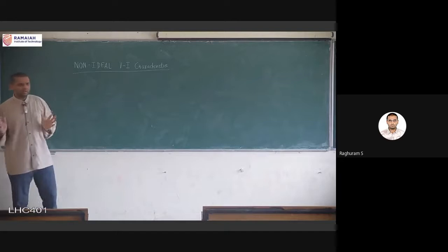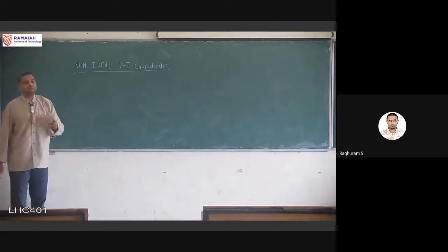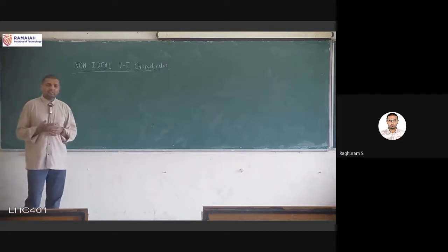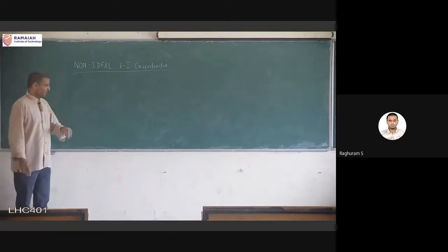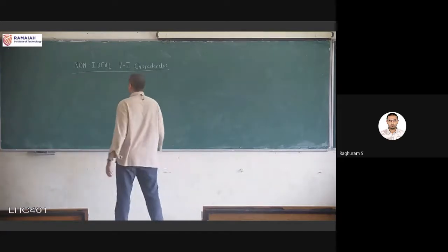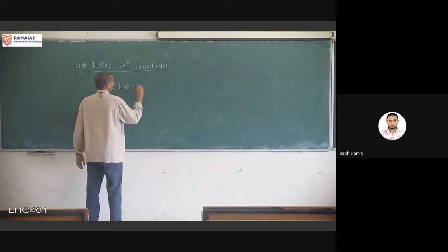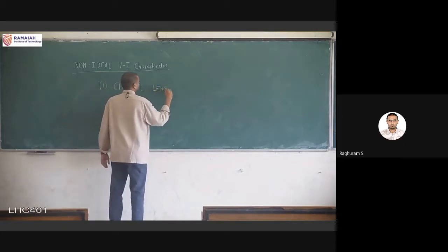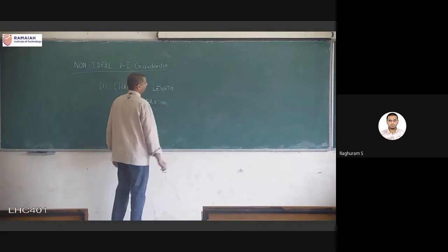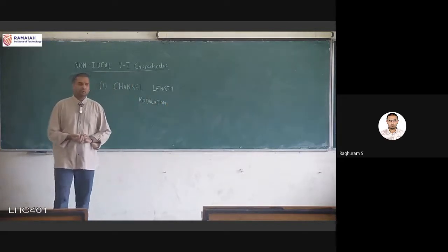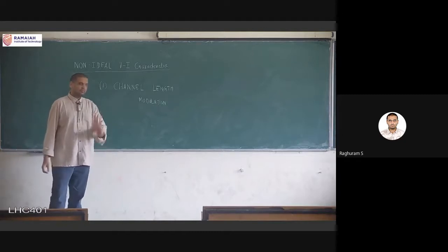The hand calculation, our accuracy is okay, but suddenly if I see a VI characteristic and it looks very different from what we have been drawing, we have to know what the reasons are. Okay, there are many reasons. We are just going to look at a few of the reasons why the real current is differing from what we have calculated. So the first one, and in my opinion the most important one, is called channel length modulation. This is very common. This is just so common that the equation itself we have to slightly modify.